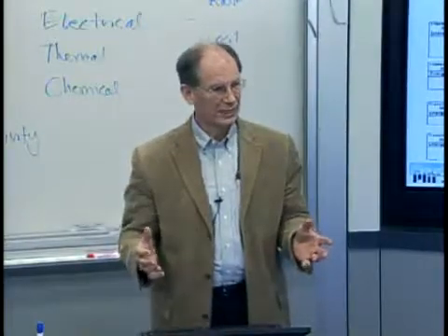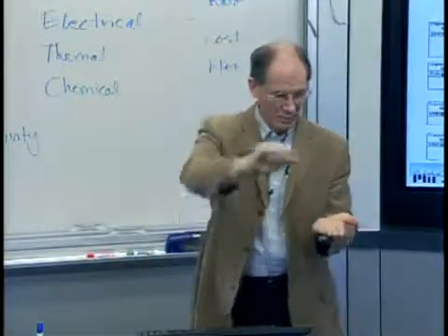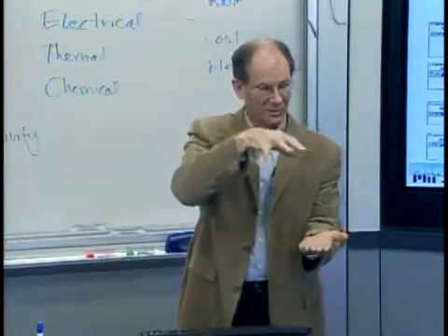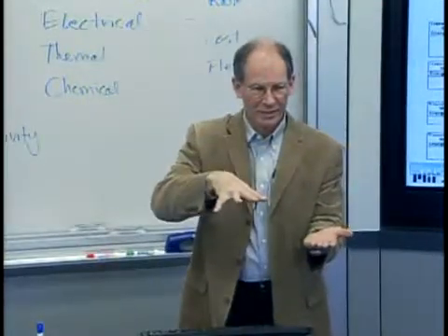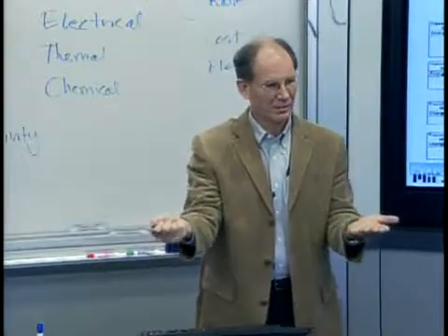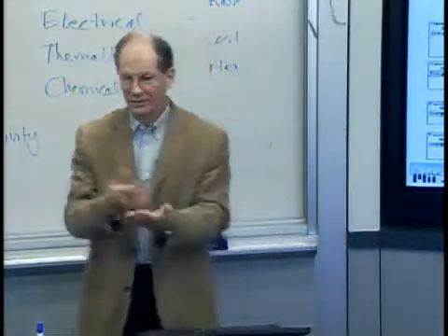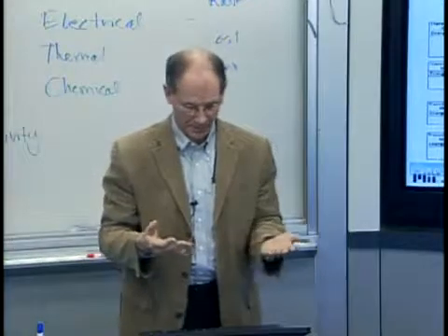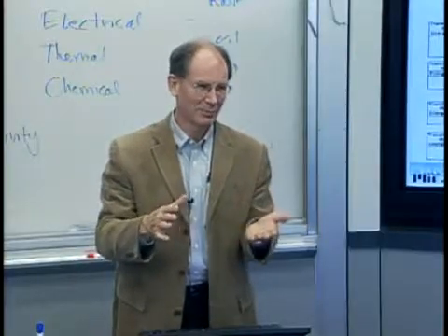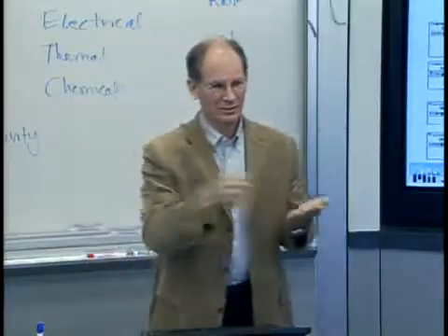We also do, in fact, I was here last night listening to a PhD thesis from Singapore where what they did is they took a mold, poured UV curable polymer on it, flashed it with a UV lamp over the whole thing for about 30 seconds or something, I think, and then pulled it apart. And it was all about the mold quality and filling and that sort of thing. A good percentage of her thesis was about making the molds. And how well could I extract this thing from the mold?